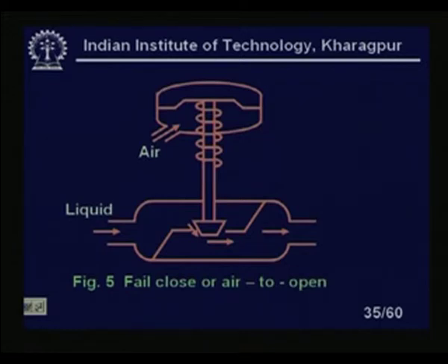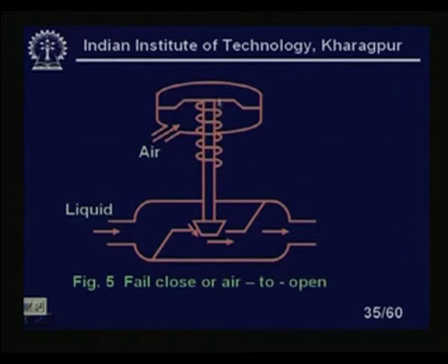Here what will happen, you see the valve will be always closed like this one, because this spring will always try to open. The valve plug will always sit on the seat. There is a seat, so the plug will always close the flow, right. Normally if there is no air pressure, the spring will try to open, clear.